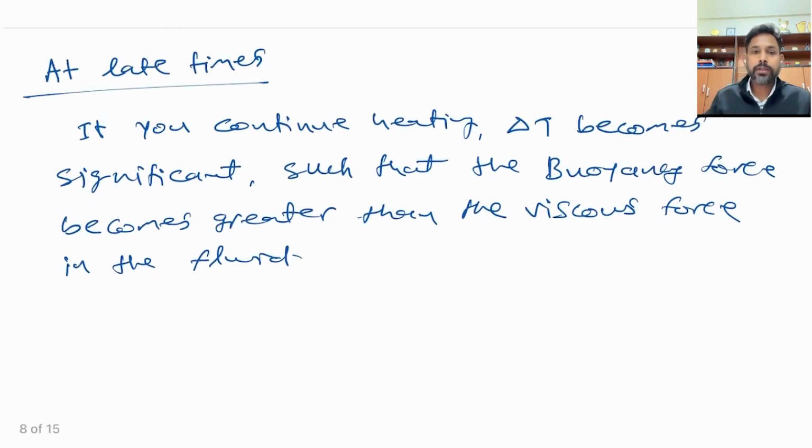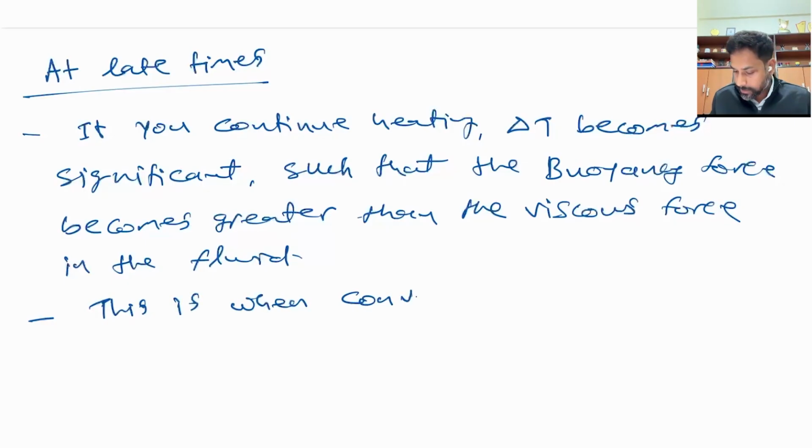Okay, so at late times when you continue heating it up, buoyancy force increases, and now there will be a point when buoyancy force in the fluid, in the bottom layer fluid, will become greater than the resistance offered by the viscosity. And when that buoyancy force becomes greater than the viscous force, convection begins. So what is convection? That is basically the motion of fluid parcels, right? So this is when convection begins.